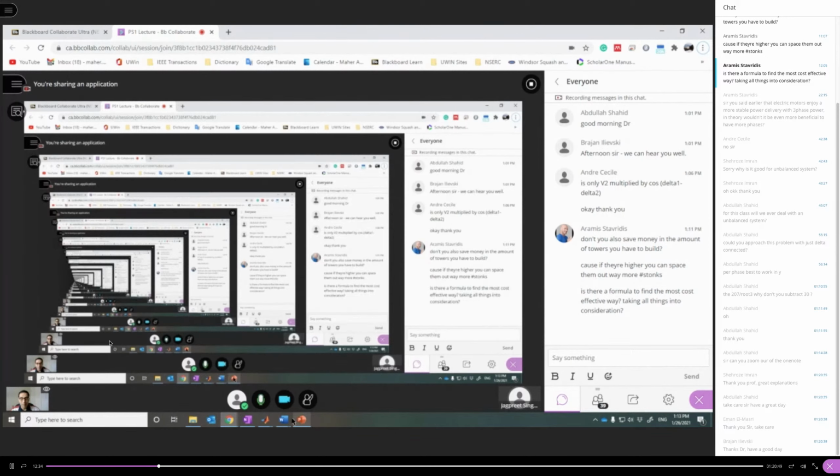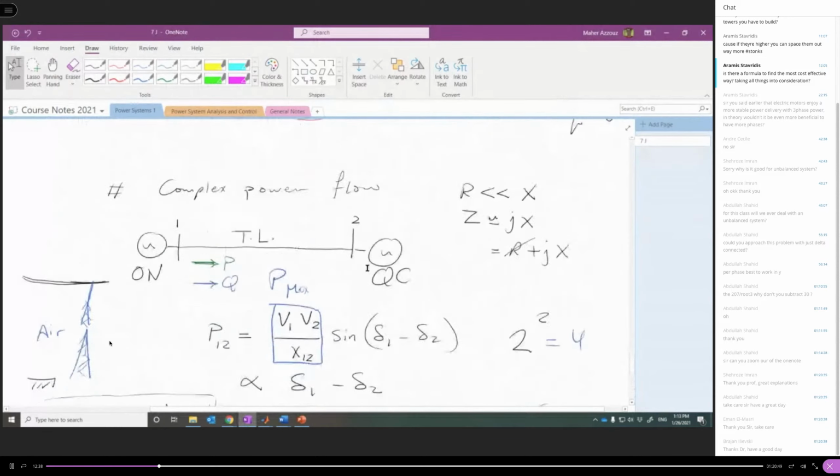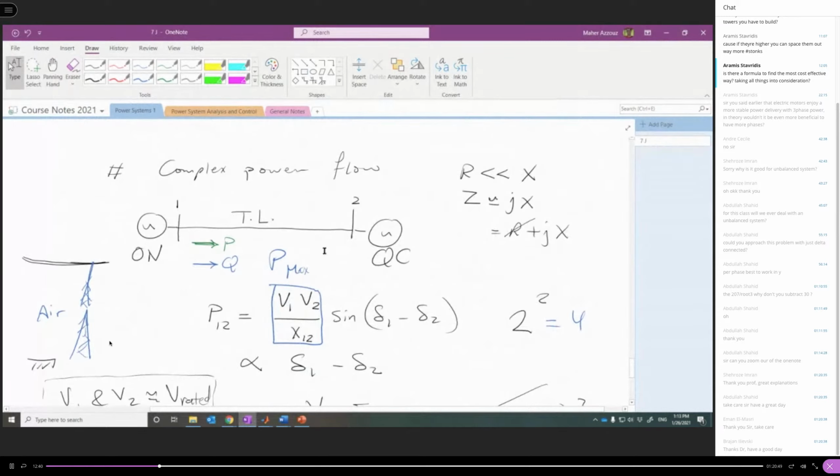So this is a point that I didn't talk about, but let's say we increase the voltage, so we could increase the power. But what happens if we have a fault here? If there is an animal contact or a tree flashover, we didn't trim the tree limbs and branches, and as a result, a tree limb comes in contact with the line and causes a short circuit.